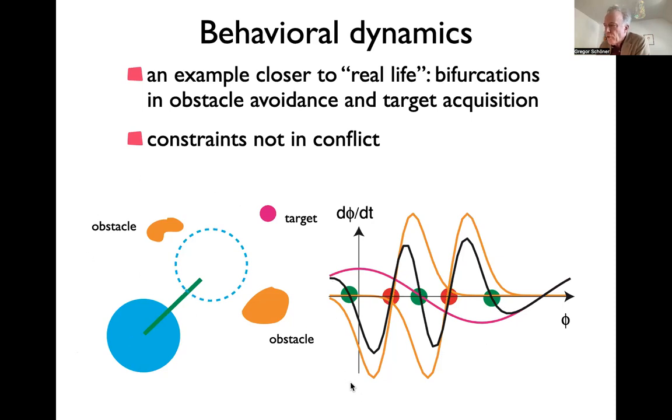They emerge from the fact that the individual forcelets, just take this forcelet as an example, have some kind of semi-attractor on their outer limit. If you just look at this orange curve here, you would say this is like a negative slope. It doesn't go through, the negative slope becomes tangent, and ultimately it wraps around. So that's like a half attractor, attracting from the side. It's actually the repulsion from the obstacle that is attracting toward the boundary of the obstacle.